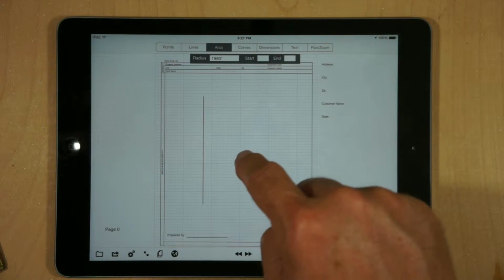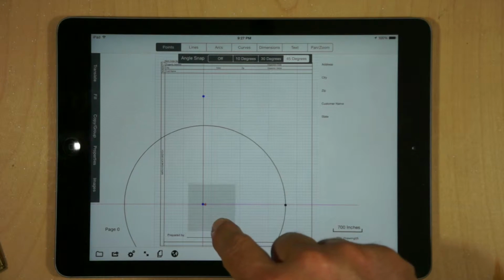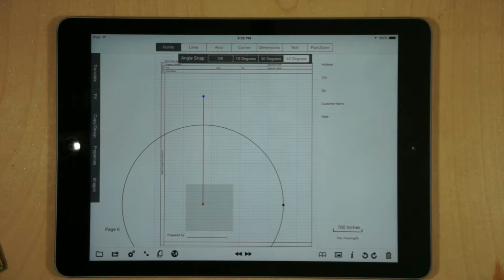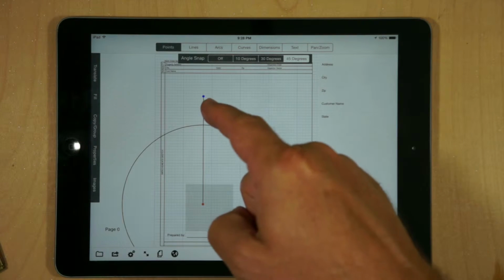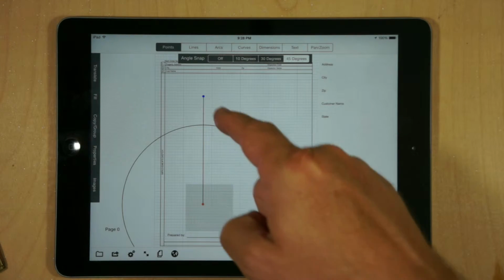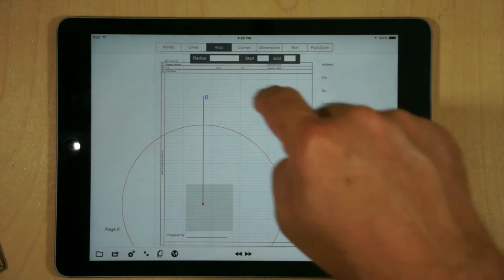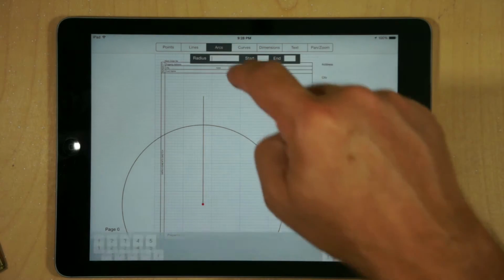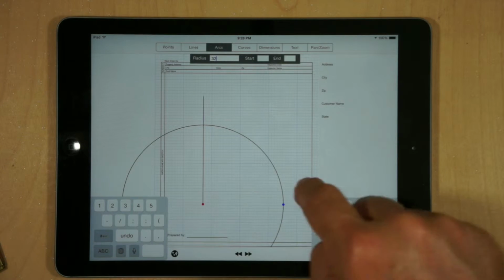And now when you drop a circle on the drawing and move it into position, we know that all the points along this radius is going to be 1,980 inches. Now, rather than just measure the top, what we're going to do is we're going to measure from this other point to this far corner and use that dimension. So what we'll do is we'll clear this line, all right, and now we'll put in the actual measurement, which was 3,260 inches.